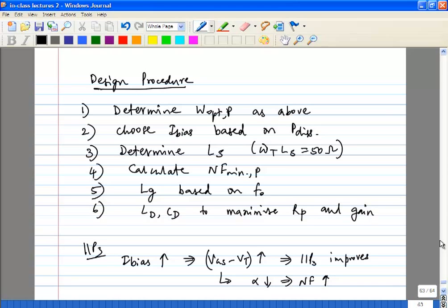If you just take any random common source, it will definitely have a much higher noise figure. What we are doing special here is making sure the input is power matched, but that has nothing to do with noise. We are also trying to make sure it is close to being noise matched.